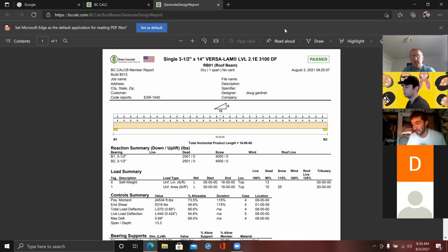Could you, as a rich guy, say, I don't want it to be an inch, choose a bigger beam because I want that to be a half inch? And I could be like, okay, great. It's just going to cost a little more money because I'll just spec a larger beam. So yeah, you're right, 1 inch is totally arbitrary. And again, this is a residential application. Maybe that number's different for that skyway at SeaTac that I showed you yesterday. Maybe that deflection could be way more because it doesn't matter if it bends a little bit.